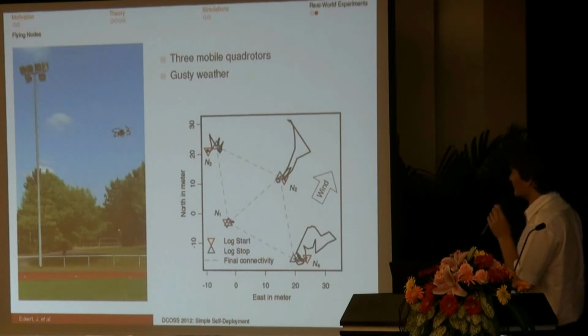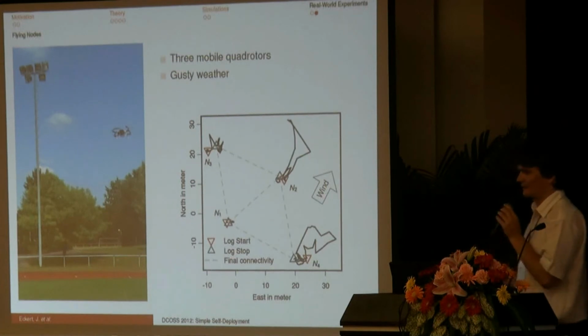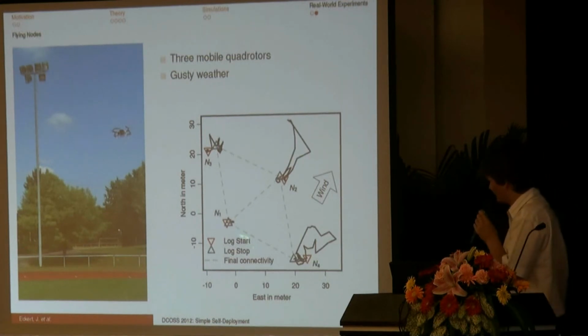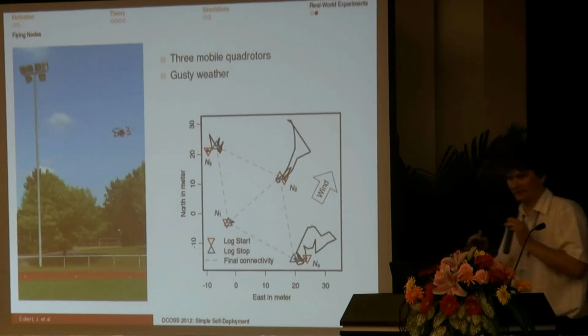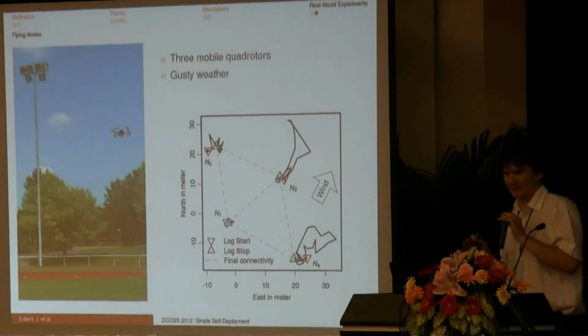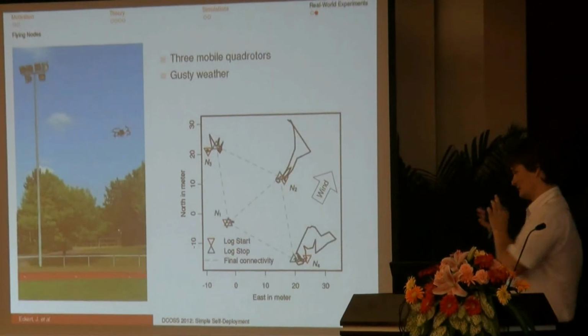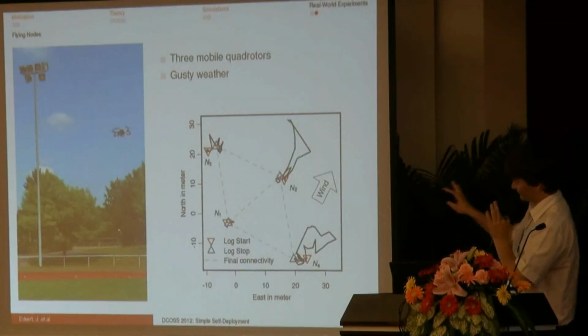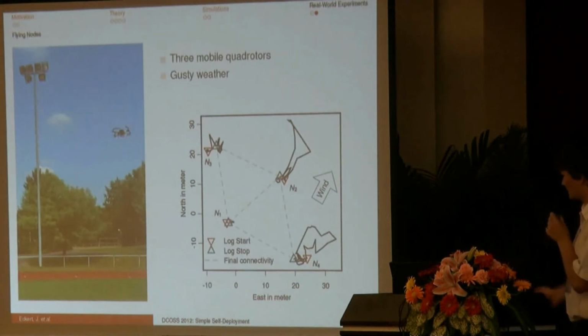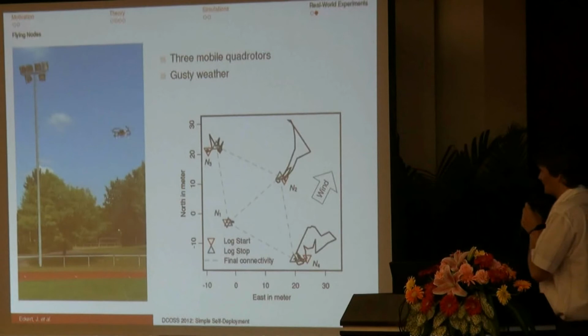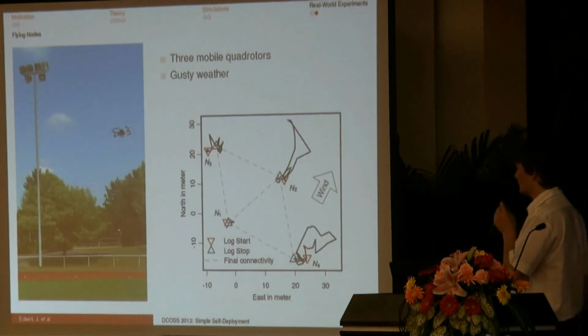And it was a very gusty day, so we couldn't let all 4 quad rotors fly. We had 1 fixed quad rotor. This is because we only use relative information amongst each other, and as we have wind, the wind would start to drift the whole network away. But this is a very short section, approximately 2 minutes, of a long-term experiment.